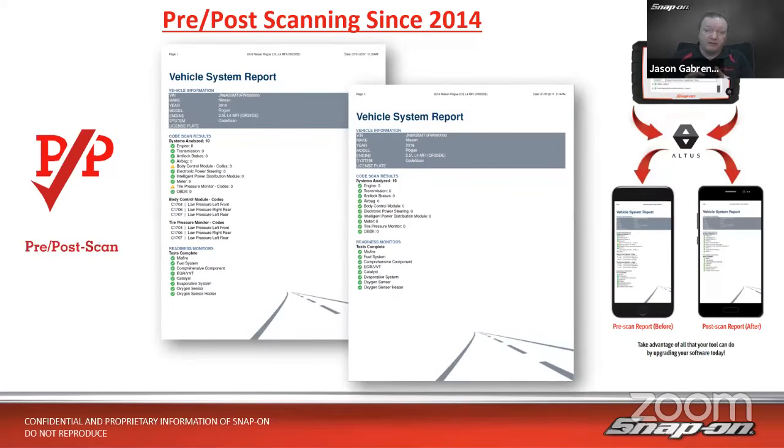And then when we're done with our repair, we want to do a post scan. We want to make sure we scan all modules again, make sure there are no codes left over, and the vehicle essentially has a clean bill of health. This is critical in body shops, collision realm, because most insurance companies require this now in order for the insurance claim to be correct. So we need to do a pre-scan and a post-scan on the vehicle.